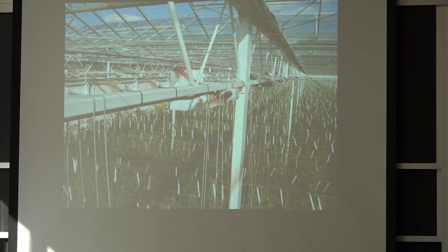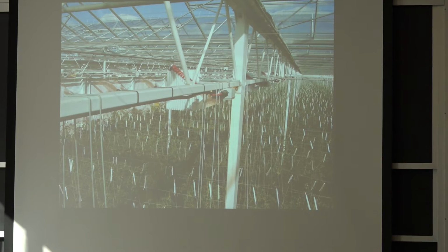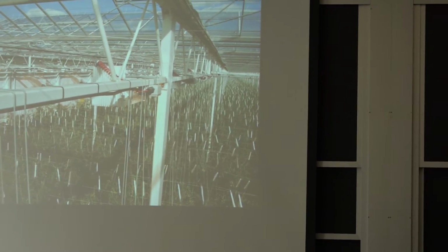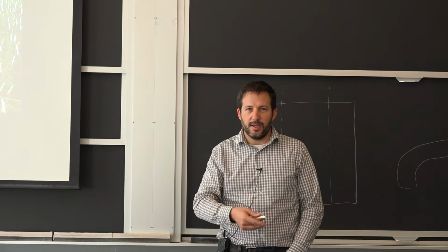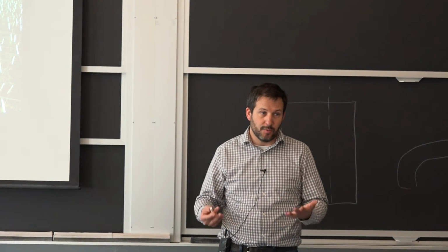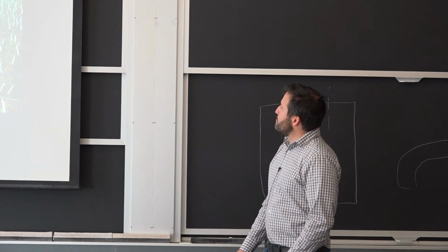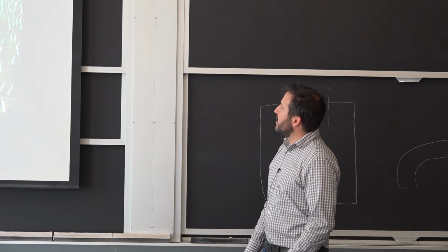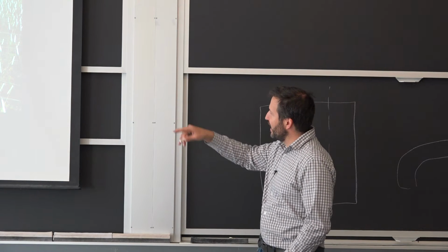And what happens is, if you have a snowstorm, you have to heat up that roof to melt the snow, channel it so you don't have too much weight. If you have a lot of snow, then the system can get overloaded, and then you have a little extra weight on the roof for a period of time. In this case, the first thing that happened when there's a little excess snow is they start breaking these diagonals.